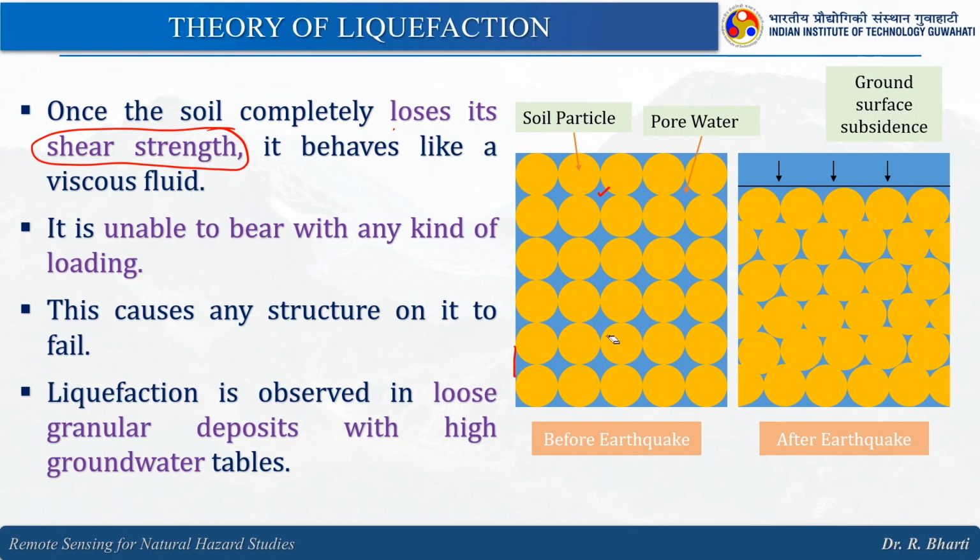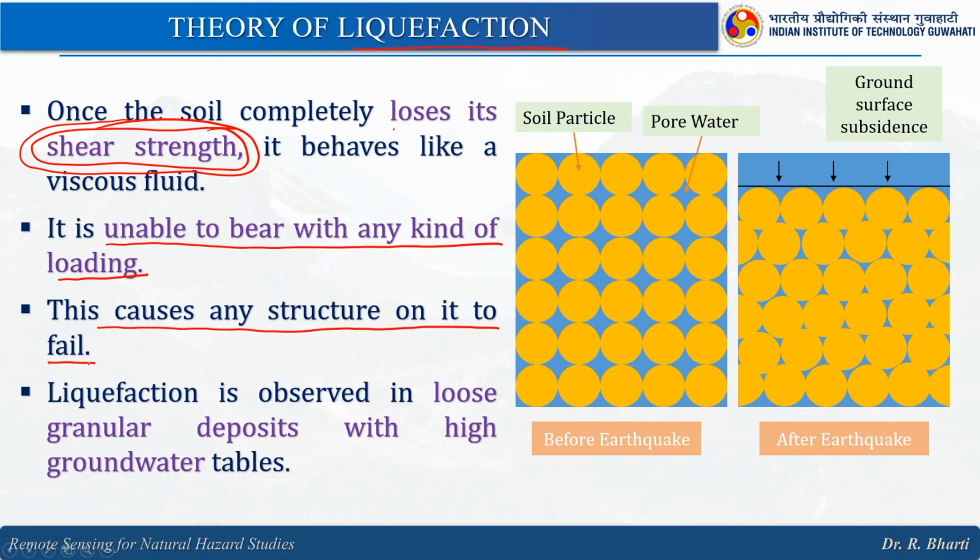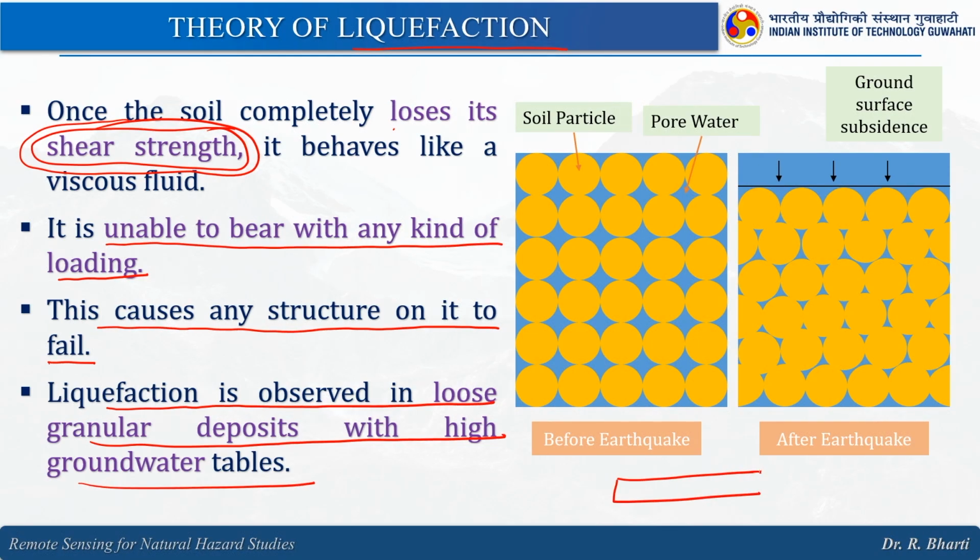So, in such a situation we observe this liquefaction. It is unable to bear any kind of loading when the soil loses its shear strength. This causes any structure on it to fail. Fail means either it will sink or it will get tilted. Liquefaction is observed in loose granular deposits with a high groundwater table, because we are talking about the soil,